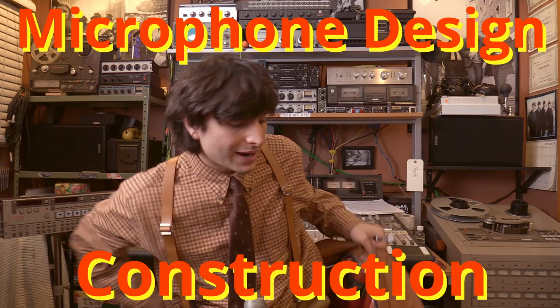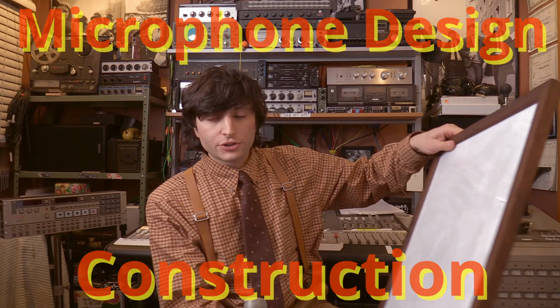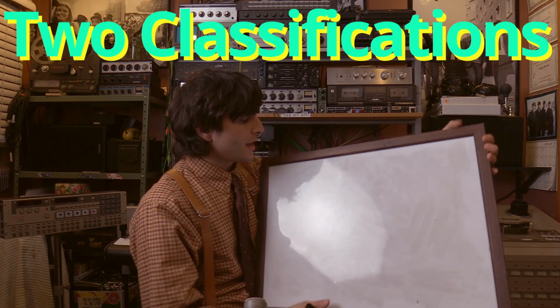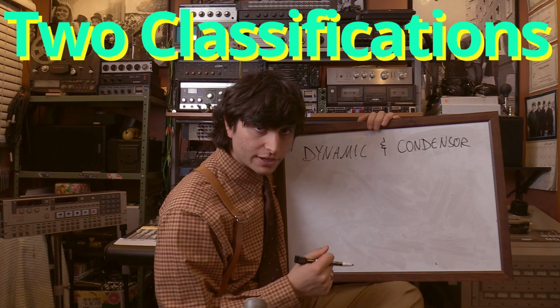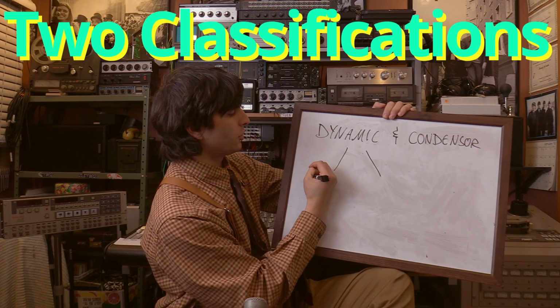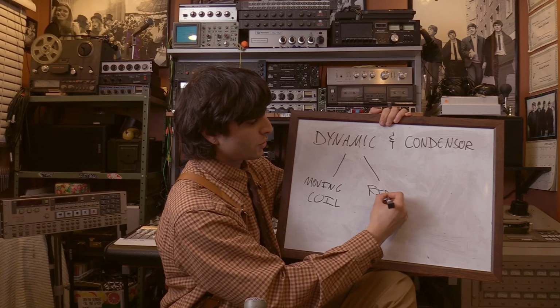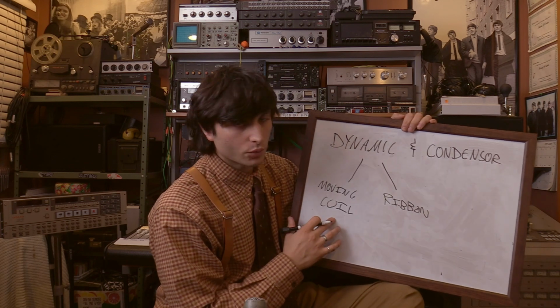Alright, that I think is enough background about sound. Let's finally get into the microphone design and construction, which is why you clicked on this video to begin with, probably. There are two major classifications of microphones that are going to be used in the recording studio, and that is dynamic microphones and condenser microphones. And I know what you're thinking, Mario, you forgot ribbon microphones. But really, what we think of as dynamic microphones are actually called moving coil microphones, and ribbon microphones actually work on similar principles that a moving coil microphone works on.